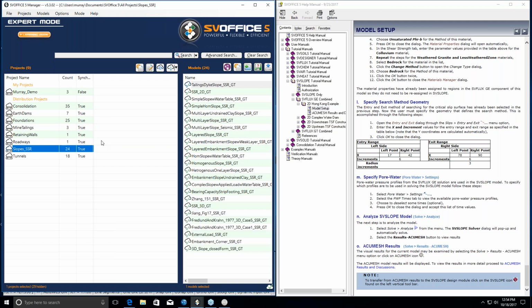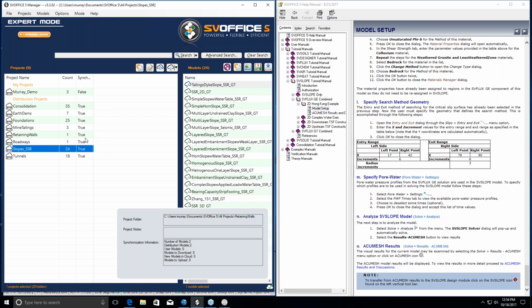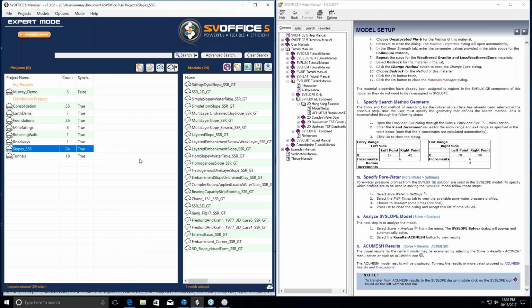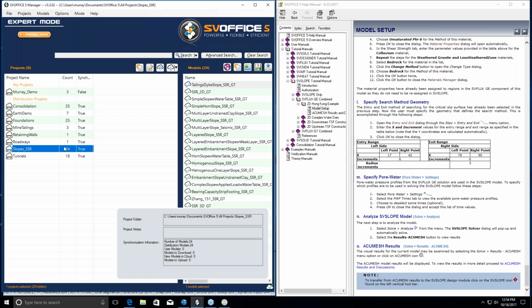One question is, why is the critical slip surface on day 2 smaller compared to the others? That's a result of the resolution that we've analyzed at. We ran one model ahead of time here, and if you pick a finer resolution on the pore water pressure changes, you don't get that for some reason. So it's just a matter of the resolution that you pick for the pore water pressure changes versus time.